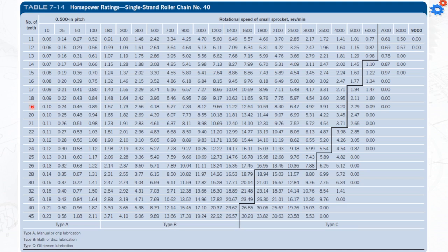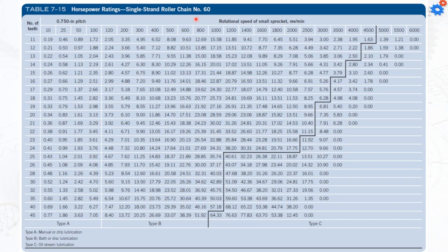Then I will choose the number of teeth. Again, this is sometimes going to be located between 18 and 19. Usually we're going to round up. Now, another thing, actually you can choose either, and then the center to center distance will guide you through this process. And that's for the type 60.